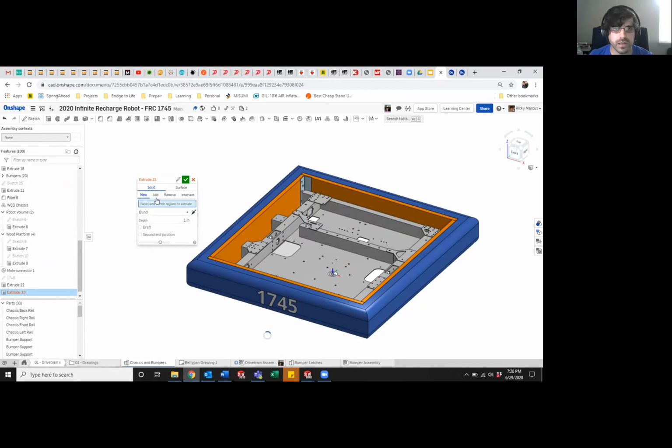This is a little bit different from SolidWorks, but not necessarily different from other CAD packages. Your add and your remove are both considered extrudes. You can also do intersections to get even more complex geometry. All this is pretty powerful, with standard constraints when you're extruding, and then you can select the bodies that it's merging with.